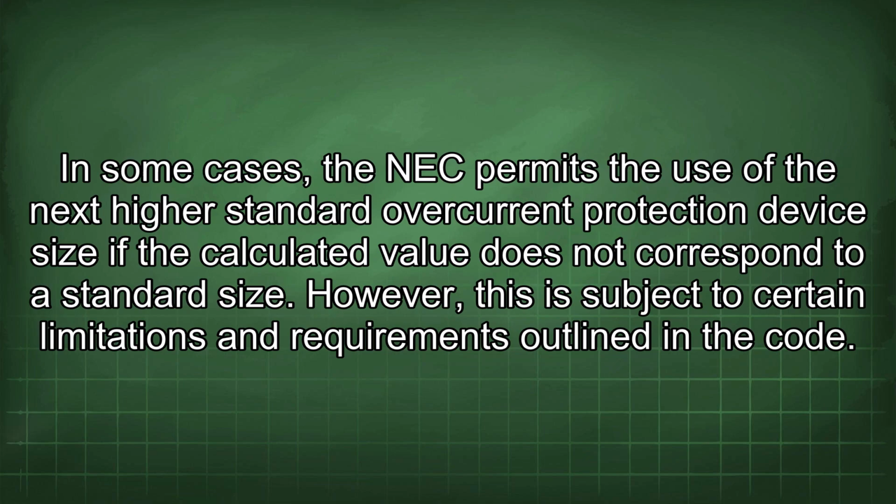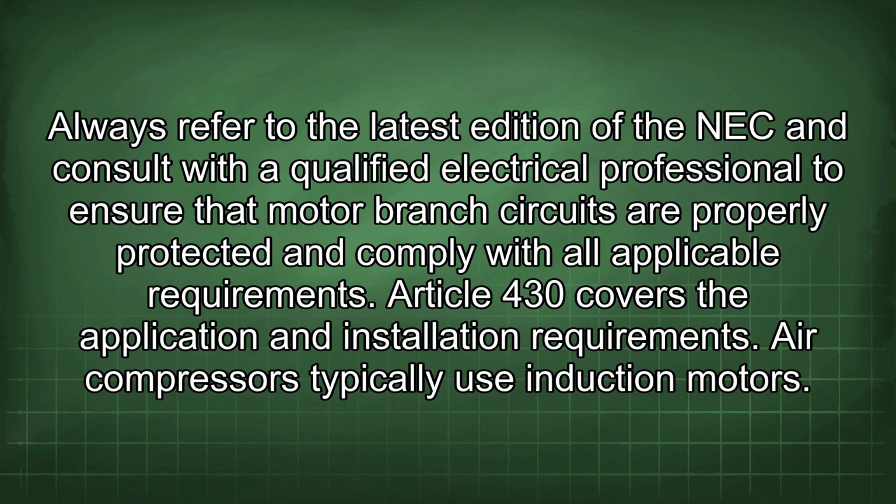In some cases, the NEC permits the use of the next highest standard overcurrent protection device size if the calculated value does not correspond to a standard size. However, this is subject to certain limitations and requirements outlined in the code. Always refer to the latest edition of the NEC and consult with a qualified electrical professional to ensure that motor branch circuits are properly protected and comply with all applicable requirements. Article 430 covers the application and installation requirements.